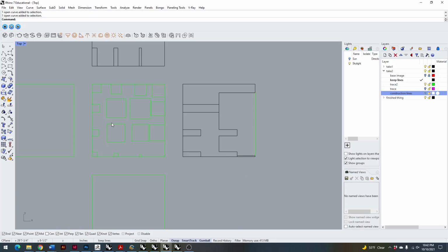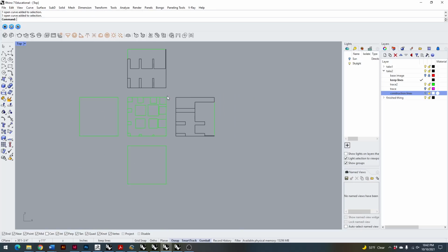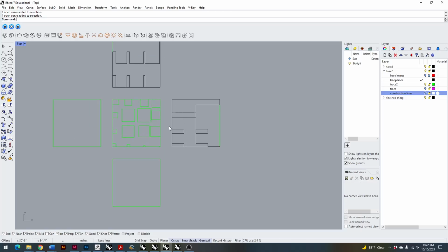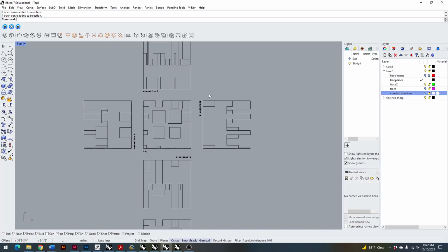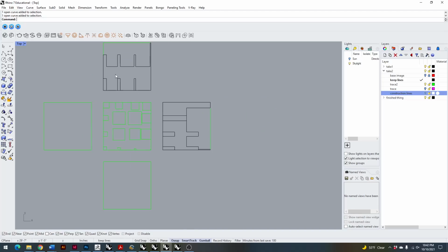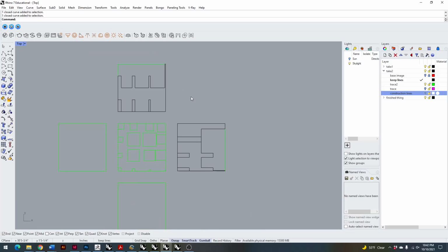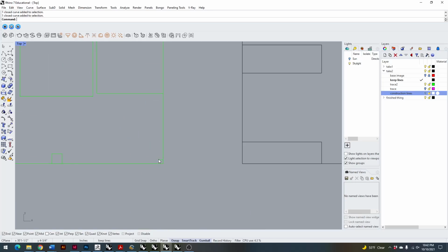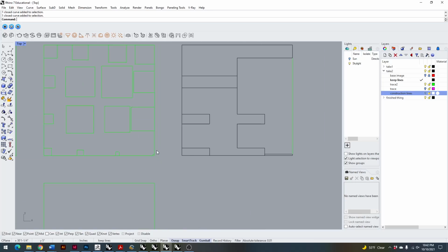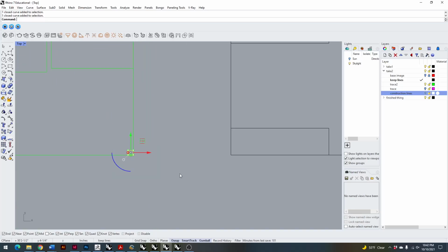The next step, assuming that we're done with all of this, like we've completely described all these drawings, we're finished up. The final step here is using then the three-dimensional object to set line weights. For example, if we know that this nub here, this skinny one, extends all the way to the top, in our topmost view, or plan, this will be the darkest line because it's the closest to the viewing plane of the orthographic drawing.